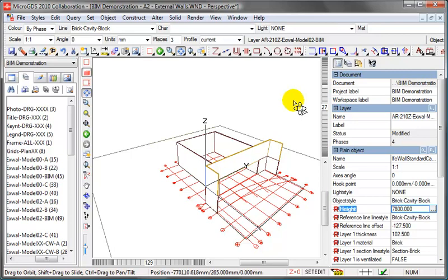The wall standard case, that is the IFC definition for these walls, requires the wall to be the same section throughout their entire length. So you have to find another way of causing them to follow roof slopes and such like. So we're going to use a different technique for that. You can't actually create the wall to the shape at this stage.